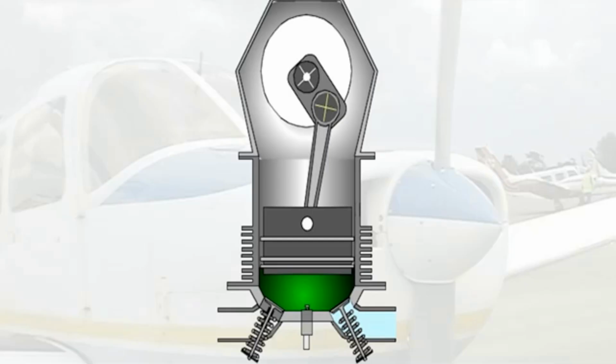Because it's incompressible, if oil is trapped between the piston and the cylinder head on the compression stroke, a hydraulic lock will be formed. If the starter motor is being used to start the engine, then something will have to give. The piston might break, the connecting rod might bend, the cylinder may be torn from the crankcase, or the crankshaft may break. None of these is a pleasant prospect.